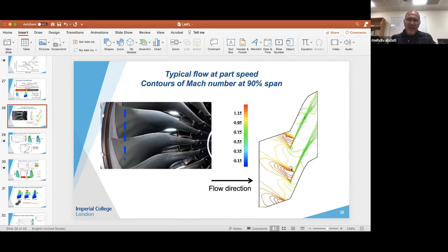Moreover, another thing that I found from my experience, I've always worked on non-linear and linear CFD codes, is that a proper phase lag boundary condition between the two blades would give very similar results. If you feed the same steady CFD solution to a linear time domain computation, a non-linear time domain computation and a linear frequency domain computation, the results are very similar because the vibration amplitudes usually are quite small.